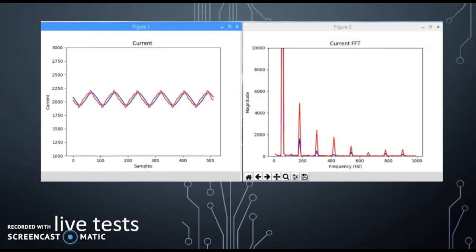So our plan is to develop a prototype that when it detects an increase in current can filter out the prior existing harmonics, look at the net change to identify appliances by their unique harmonic signature. Now I'll turn it over to Brandon, who's going to talk about identification by start signatures.